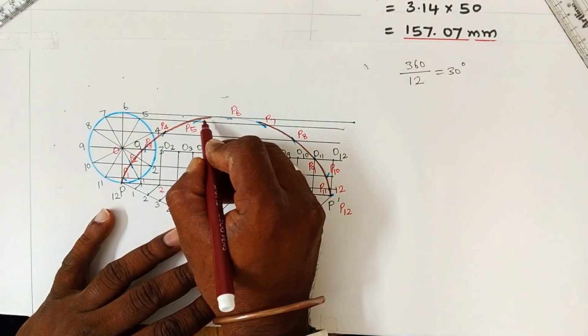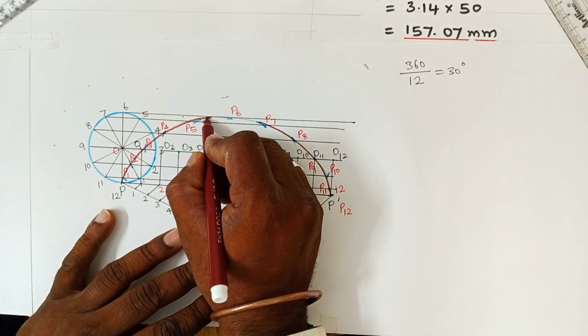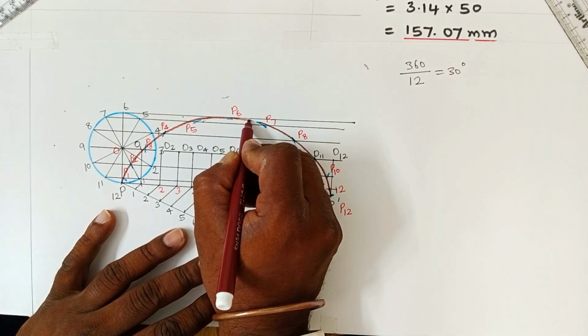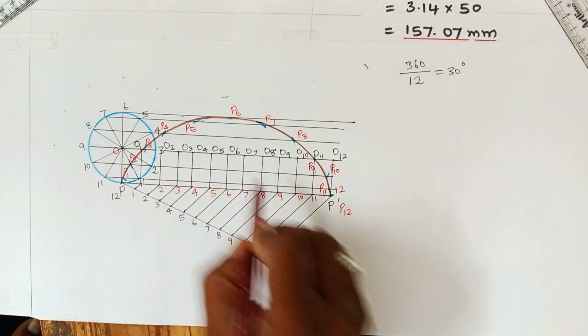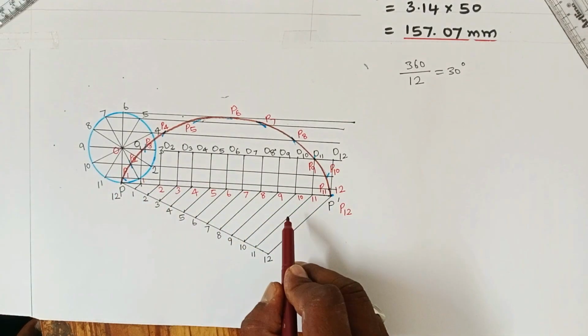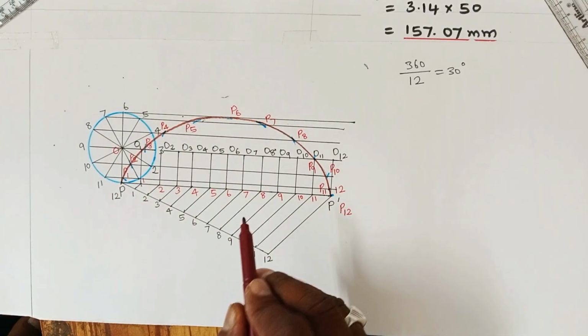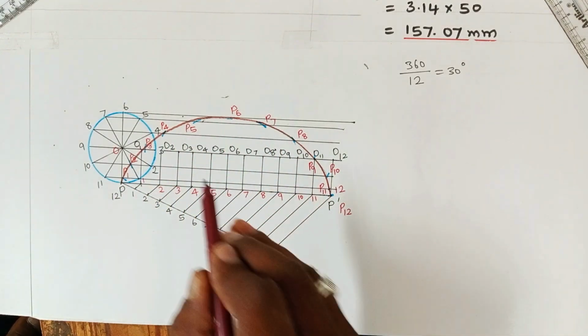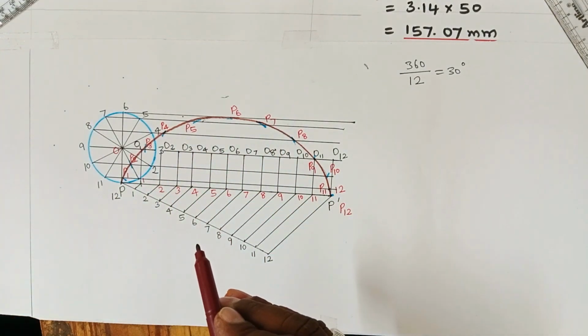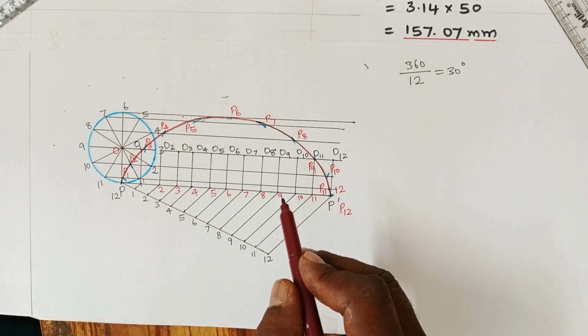Draw this curve by H or HB pencil as asked in the question. The circle, vertical lines, and horizontal lines, dividing into 12 equal parts, shall be done using a 2H pencil, lighter lines. The final curve is a cycloid of a circle. Tangent and normal you have to draw using H or HB pencil, so they appear dark.